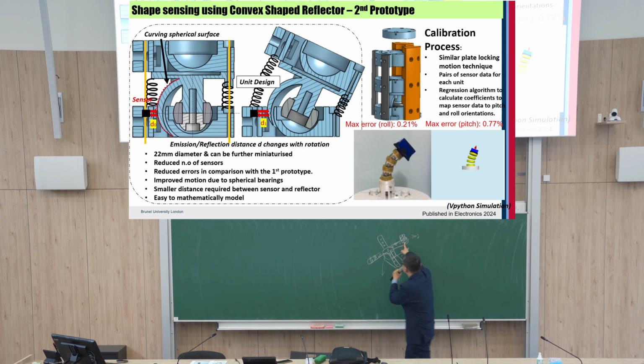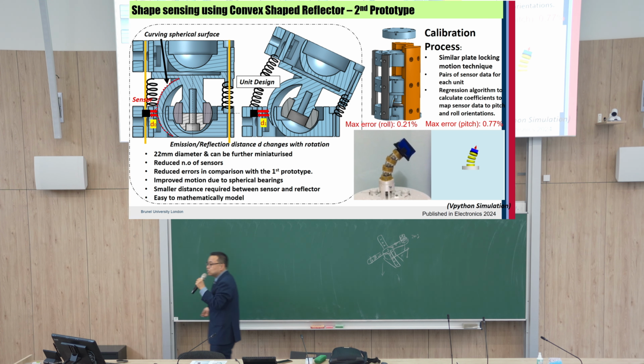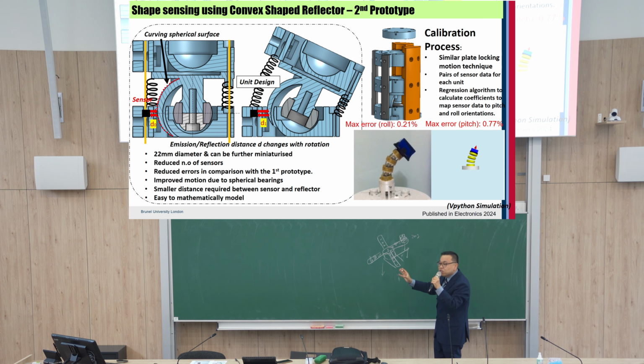These ranks, and everything else we can do automatically. But once we finish this one, we also mount it from here to here, here to here, and each of all this calibration has to be done. In this case we will get a lot of data, and using MATLAB or Python we can calculate calibration matrices. Right? Yeah. I don't think these days the ATI sensor company is using the very conventional way.